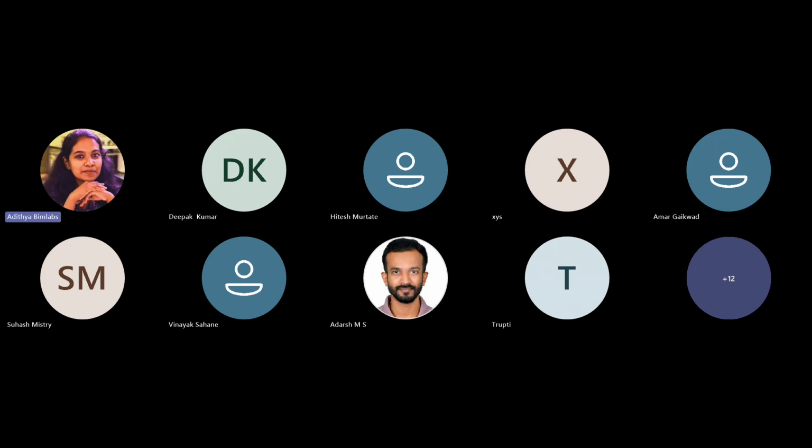And the fourth one is animator and scripter. Animator enhances project visualization and interaction with model behavior. These tools allow users to create dynamic presentations and simulate model interaction for improved project communication and planning. And in scripter, by creating scripts, users can trigger these created animations. Next, I think I will explain the clash detection.